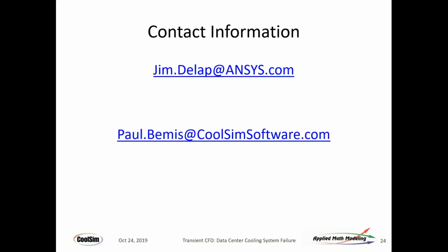Is transient analysis available in CoolSim directly? No, we don't have it in there because it requires right now quite a bit of investigation to know what's going on inside. And CoolSim is a steady state, set it up, let it go, forget about it until the results come back kind of approach. With transient, you often have to see if your time step is correct and if your convergence is good before you can take the next step, or at least you want to take a look at those factors as you pass through time, simulation time.